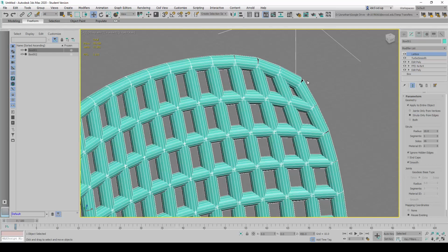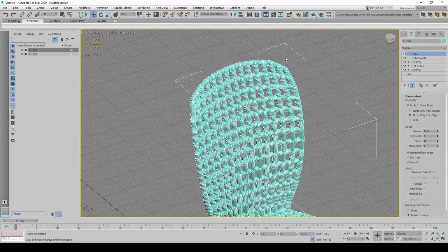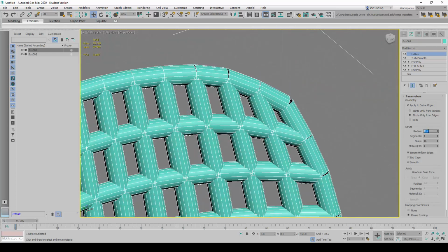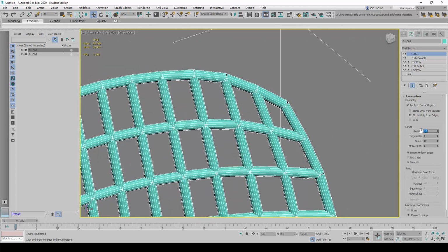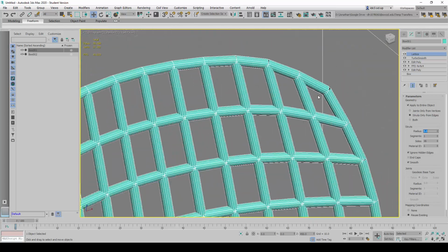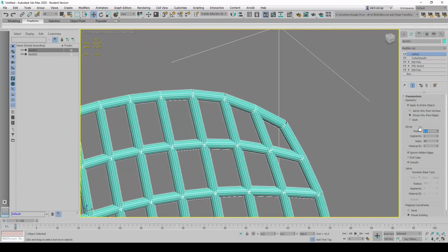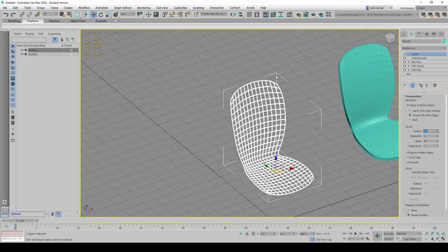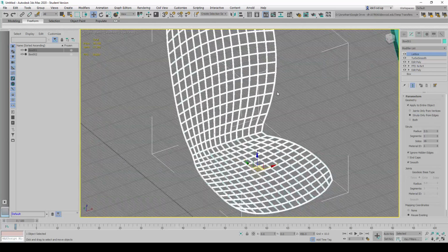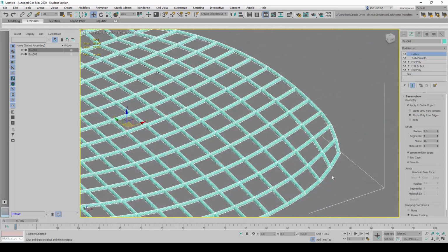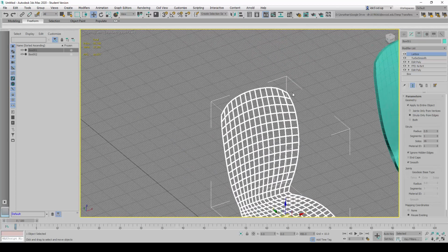And we can obviously also change the radius of the struts by changing it to say 5. So this will become a 10 unit, or 10 mm, wide strut line this way. We can make this part even smaller by changing it to say 2.5. Now it's really fine, like that. I'm quite happy to just leave it at 5 for now.